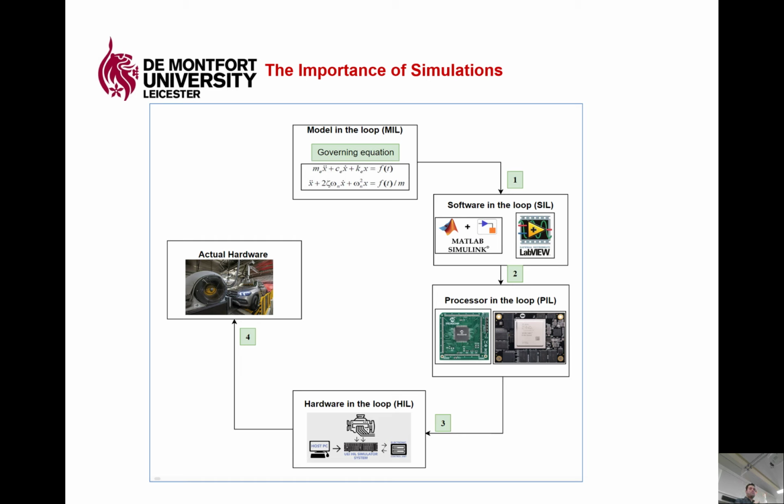So you have a system, you design the controller, you model everything, and you want to make this system go into real life implementation. For example, you have a car, you want to design a suspension system, you model your system, you do some simulation, and you want to run this model in a real life car. So how will you do that? You use a microcontroller board or even an FPGA board, like processor in the loop, and run the first version of your control and model on these processor in the loop boards.